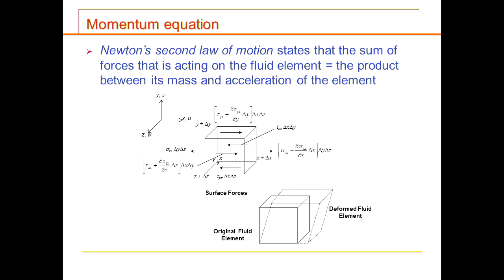So here comes the momentum equation, which is essentially Newton's second law, F equals ma. But it's not actually as simple as F equals ma, because the computer cannot solve that. So what we need to do now is to further break down the mass times acceleration part, and also identify all the acting body force or the surface force on the fluid element itself.